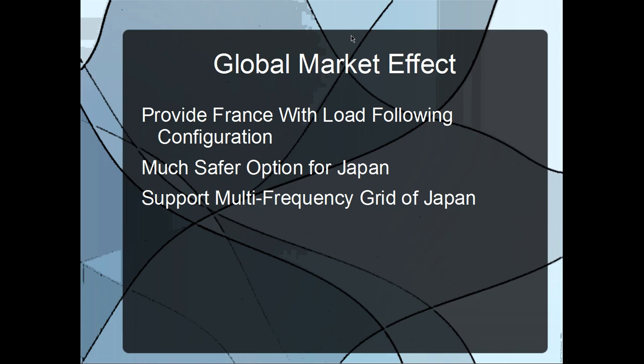electric power availability. Another aspect unique to Japan that makes it an ideal candidate for SMRs is that the electrical grid in Japan actually runs on 2 different frequencies. The electrical grid in eastern Japan runs at 50 Hz, while western Japan runs at 60 Hz. The limitations associated with the electrical grid being run at 2 different frequencies contribute to difficulties in the efficient dispatching of electrical power throughout Japan. SMRs can help to alleviate some of this problem due to greater flexibility and incremental capacity generation. As older plants are retired, they can be incrementally replaced with SMRs, which would allow Japan to integrate their electrical grids over time.